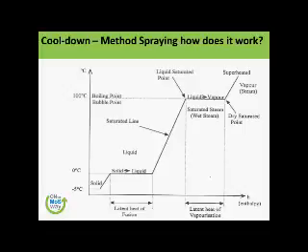So this is the liquid saturation point, and this is the dry saturation. So folks, this line here is the enthalpy line. Heat inlet or heat outlet. If we go that way, it is heat outlet. If we are going this way, it is heat inlet. And that is the basis of our enthalpy diagram.